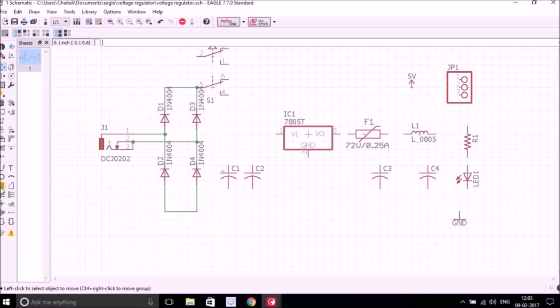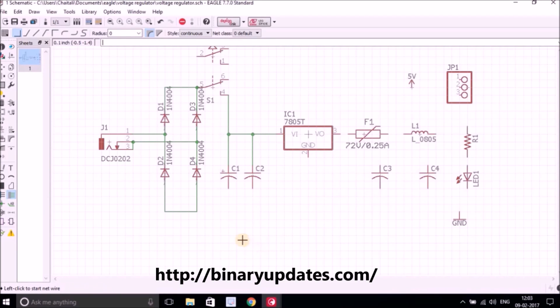So before I connect, I go back and choose the net class again, and then connect this way, and it goes straight to the input pin of the 7805 chip. Then let me connect this pin as well. Okay, it seems pretty cool, but I'm not happy with a few components here, so let me select them again.